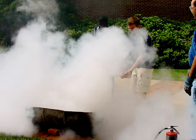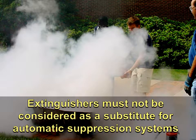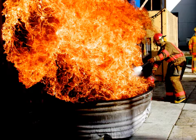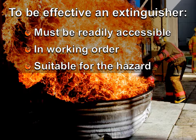Portable fire extinguishers can provide a first defense for fires of limited size. Extinguishers must not be considered as a substitute for automatic suppression systems. To be effective, an extinguisher must be readily accessible, in working order, suitable for the hazard, large enough to control the size of the fire, and the user must know how to operate the extinguisher.